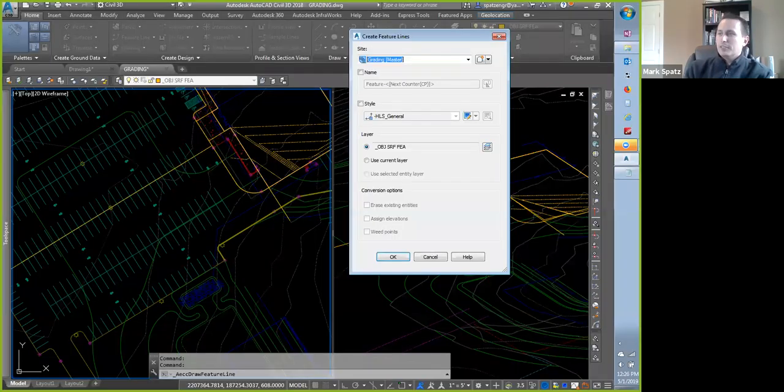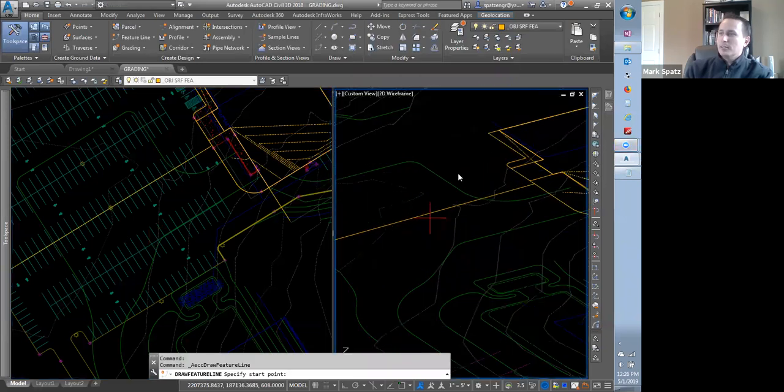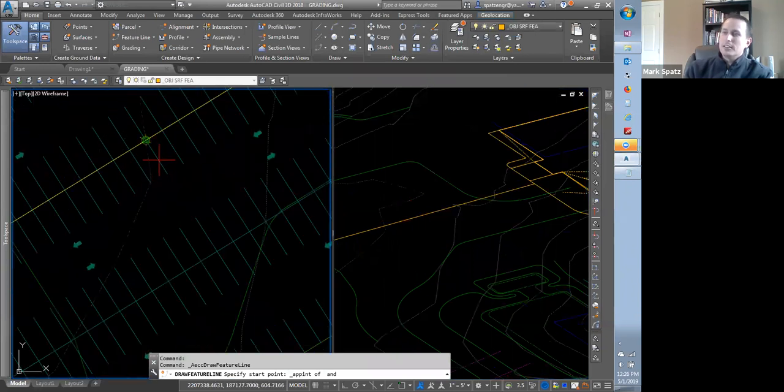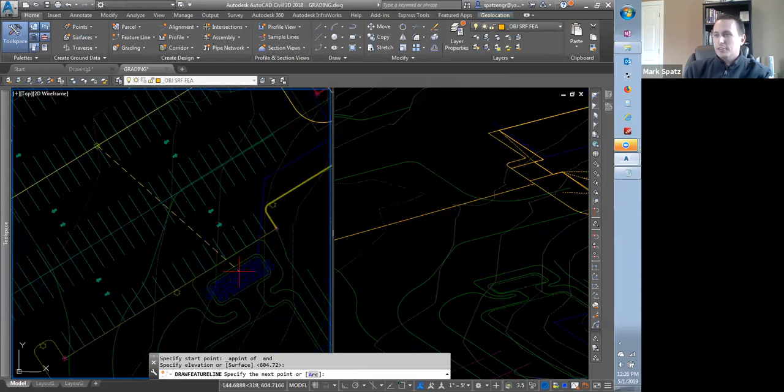Resume. Use my feature line tool again. I want to do that same thing again, where I want to do the parent intersection of this parking tree feature line, and then I'm going to use one of these space things. Hit that. That tells me that elevation. Then I'm going to bring this down across here, and I'm going to go right to the center of where we want to let water into this forebay. I'm going to come right to here. I'll do an endpoint snap to that. And I'll make my cross slope -2%.